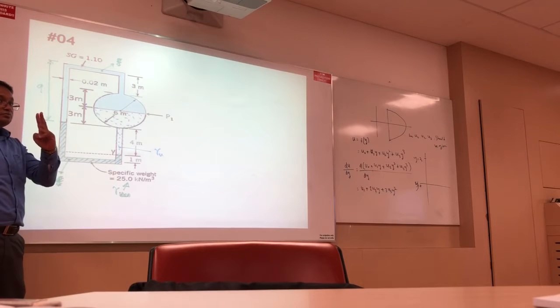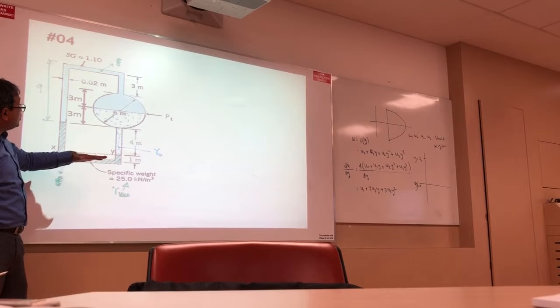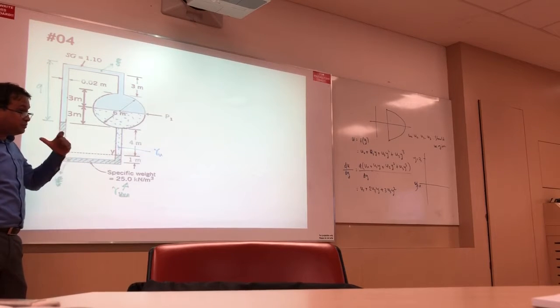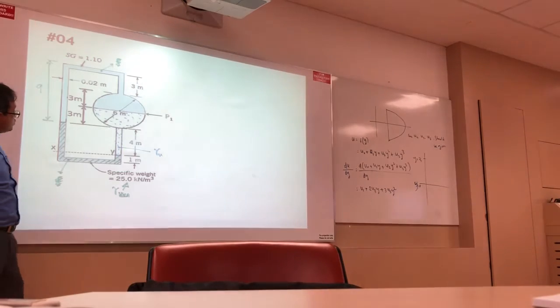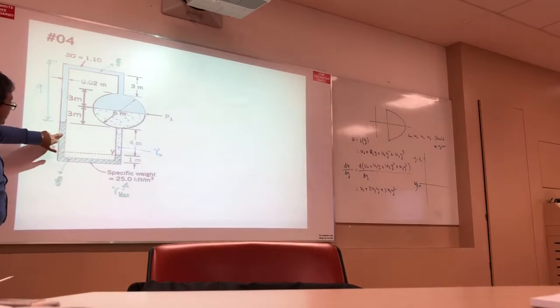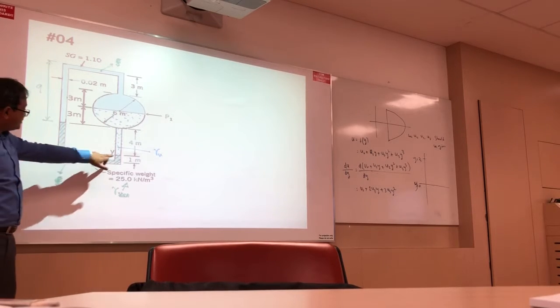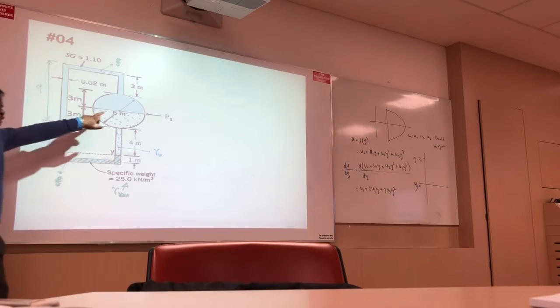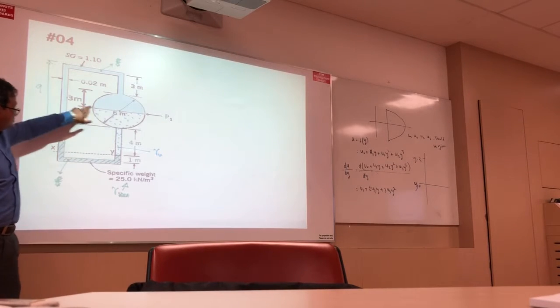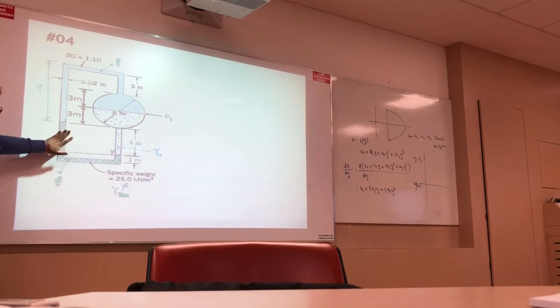Three types of fluid. So when you calculate, all three fluids' effects must be there. Otherwise, if you choose this point and that point, different. Cannot. Not good. Not the same pressure. If you choose this and this, same fluid, right? If I choose this point and here, you cannot solve it, because you miss this fluid.